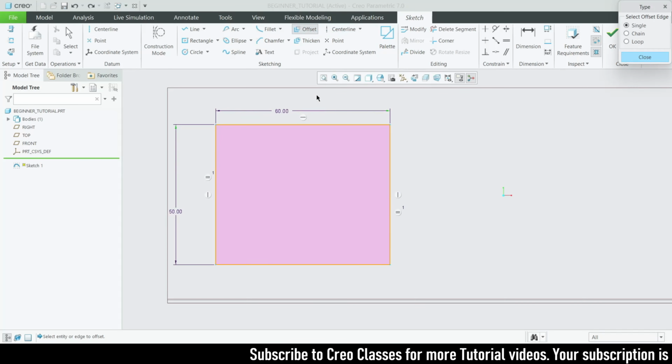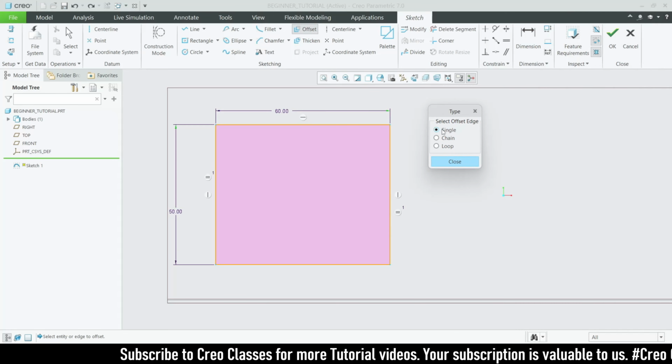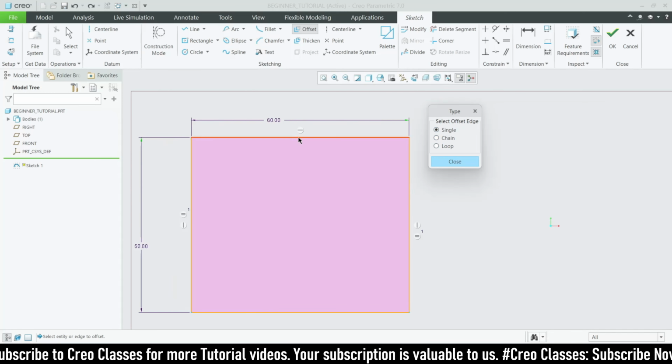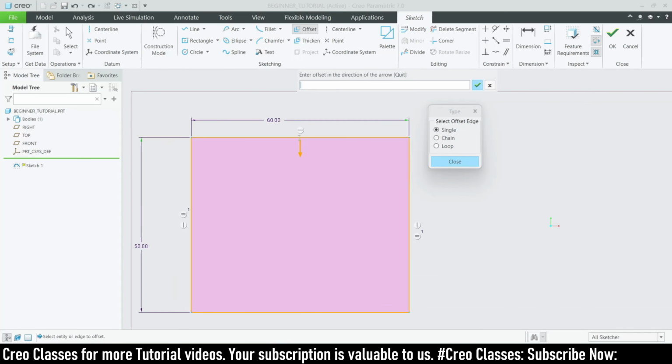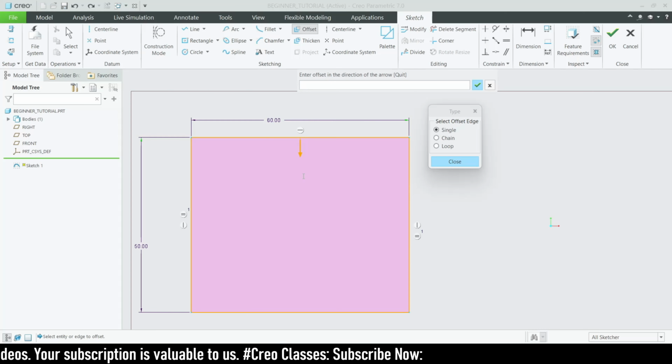At first we need to select the offset option, and then you can see a pop-up window showing single, chain or loop. Let's see single. If we click on this line, it will be taken as a single line. This arrow mark means we are going to replicate this line towards the bottom.